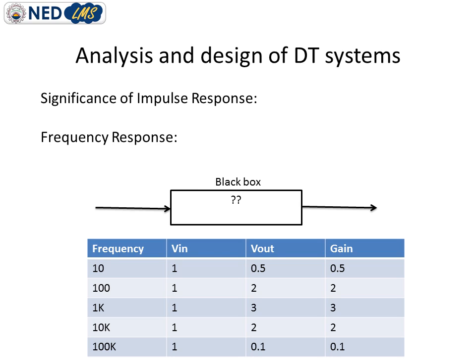Now I will further increase the frequency to 1000 Hz, and at 1000 Hz I will again apply the same voltage signal, which is 1 volt, and I will observe the corresponding output, which is 3 in this case. With the help of input and output voltage information, I will again calculate the gain, and the gain appears to be 3. So the same procedure is repeated for other frequencies as well.